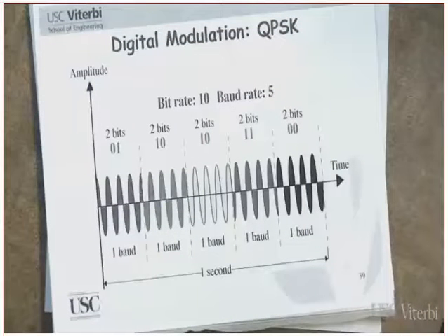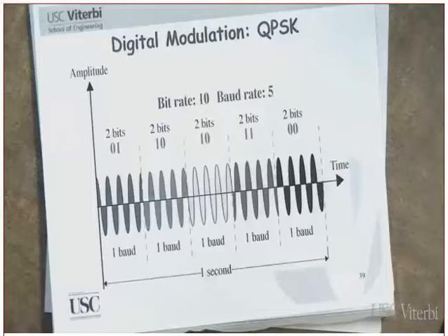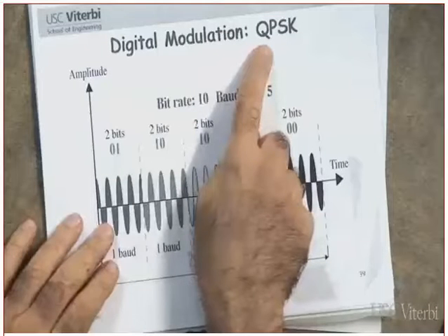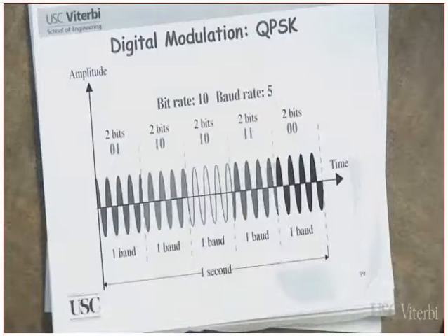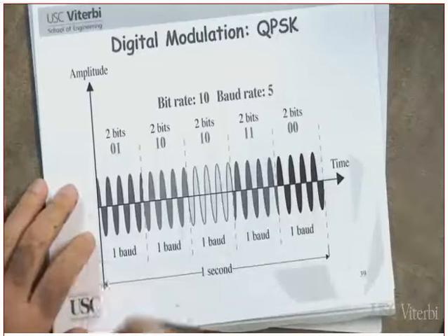Remember, the transmitter or the device is generating bits in a serial fashion. Are you following? A serial fashion, one bit at a time. One bit goes into the modulator, nothing comes out. What happens to that bit? That bit is buffered inside the modulator. So you can tell that once you have multi-level modulation, you are going to have what? Complexity in the modem design, because you need buffering inside. Clear? Okay. Second bit goes in, one signal will be generated.